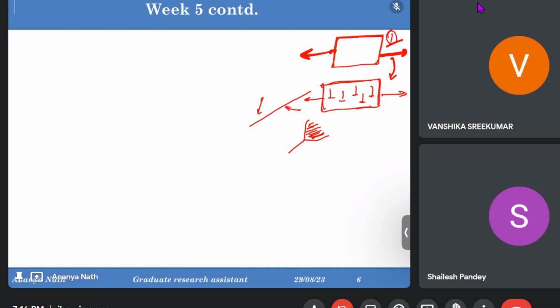So solute atoms find it difficult to find a vacant place in the parent lattice and jump in and sit there. But as this is a new phenomenon taking place inside the material, dividing the dislocation into two parts, the place in between is somewhat different from the parent metal. The situation and environment of this portion in between two dislocations is now somewhat different from the parent metal environment.